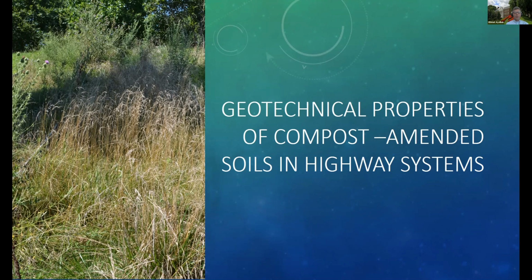And then there is always rehabilitation of these highways. In addition to that, they're building new highways. And there are county roads, local roads, and so on and so forth. Therefore, there's a lot of interest. And when we say highway systems, it's not necessarily the pavement system that we are interested in. There's basically the base and sometimes the stabilization of the subgrade underneath. And along the highways, there are stormwater systems, bioretention systems, retaining walls, and you name it. That's why the potential use of recycled materials in highway systems has received a lot of interest.